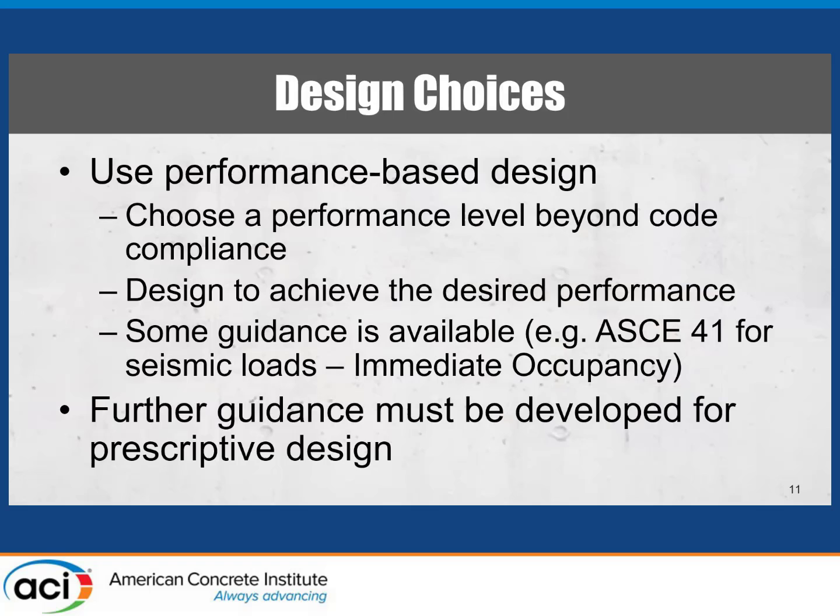So I'm going to talk a little bit, having just mentioned, about performance-based design. Obviously, as Julie mentioned, code design is generally life safety. That is, it's not intended to preserve the function of a building after an event. It's intended to prevent loss of life during the event. There's nothing that prevents you from choosing a performance level beyond code compliance and then designing to achieve the desired performance. The difficulty here is the owner needs to agree to it.